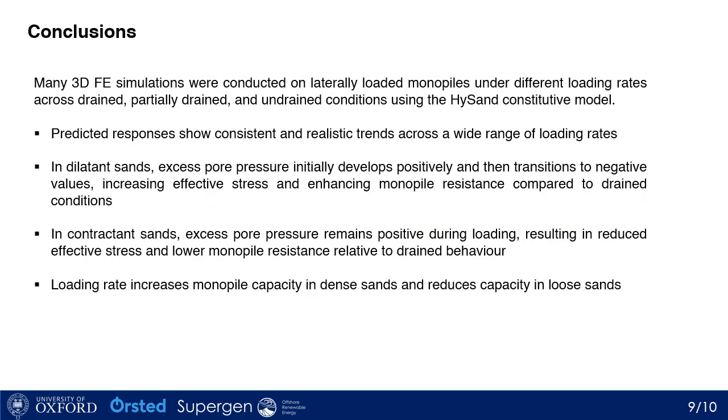Let's talk about some conclusions now. In this study, many three-dimensional finite element simulations were carried out on laterally loaded monopiles under different loading rates from low to high to simulate drained, partially drained, and undrained conditions using the Hypoplastic sand constitutive model. The numerical predictions show consistent and realistic trends across a wide range of loading rates.